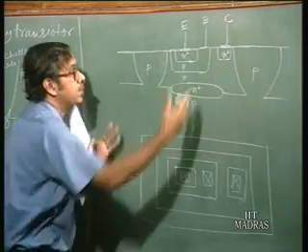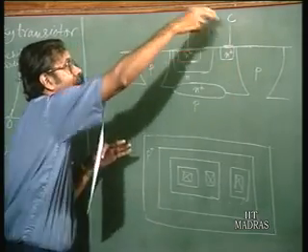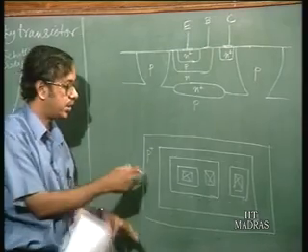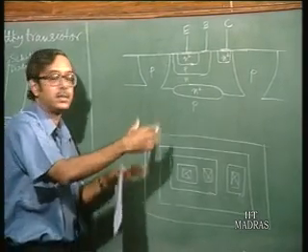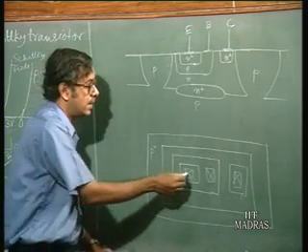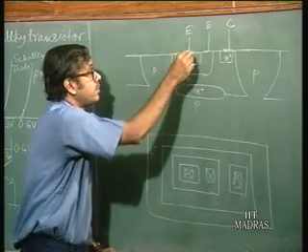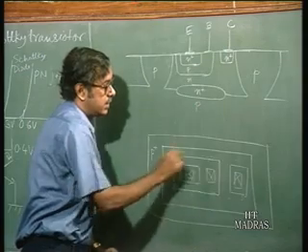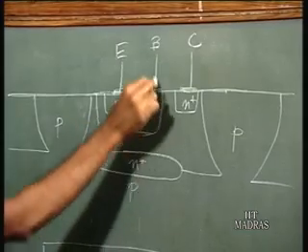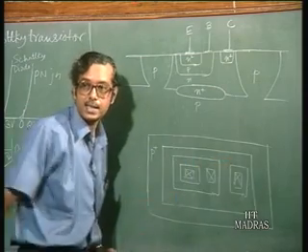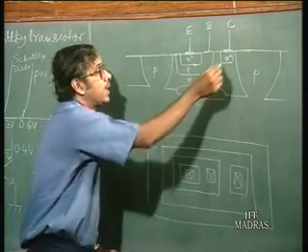Okay, and then you see the cross section. So, this is an island in which the device is formed, a p-n junction which isolates, which is actually reverse biased all the time, so that it isolates the different transistors on the same chip. Okay. So, this is the emitter contact, which is here, the base contact which is here. So, this is the base p region, and this is the n plus collector region, and this is